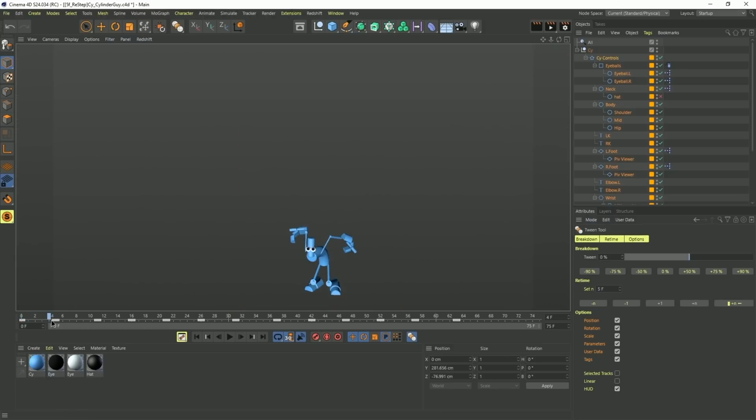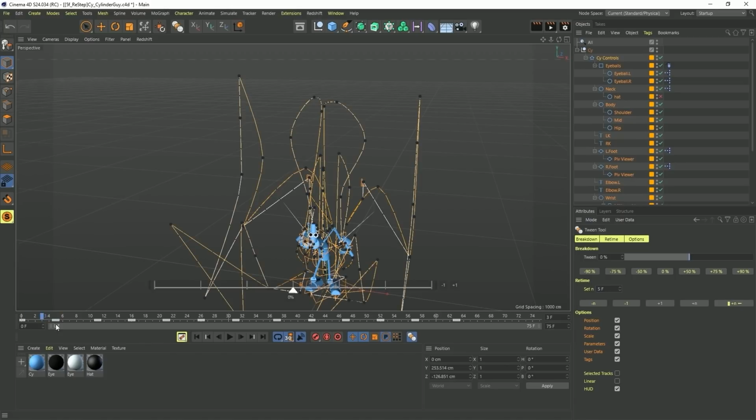So we've got this first pose where we're going from resting to the beginning of his anticipation for jumping. I would like a lot more time in there. So instead of dragging and selecting everything in the timeline, I could just have everything selected and hit this +1 button. But holding down Shift will mean everything ahead of this time will get moved forward. Let me show you. If I just hit +1 right now, you see the next keyframe is going to get scooted forward and backward. But if I hold down Shift and hit +1, then everything moves forward. And this is really nice.